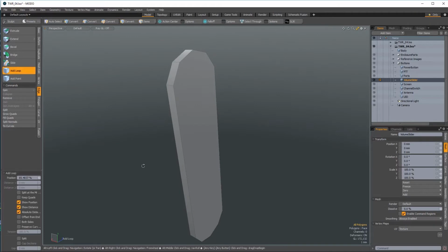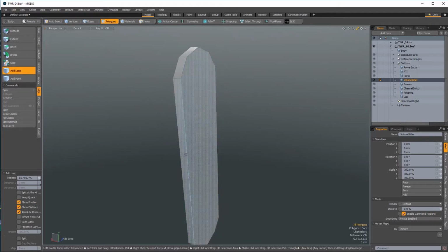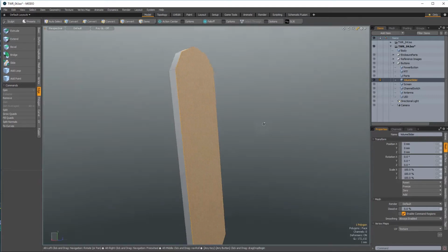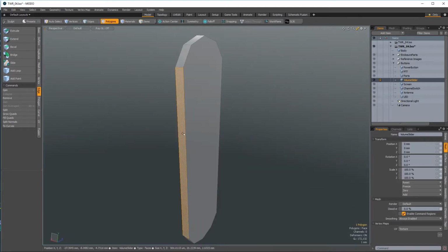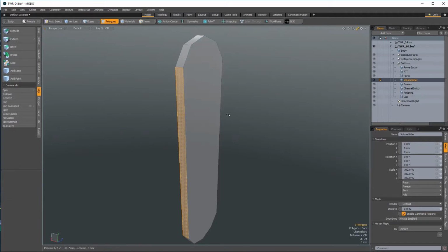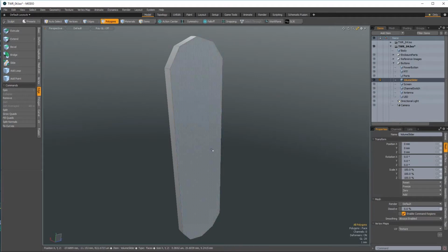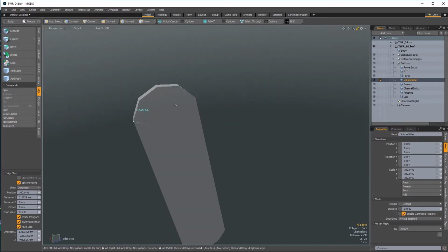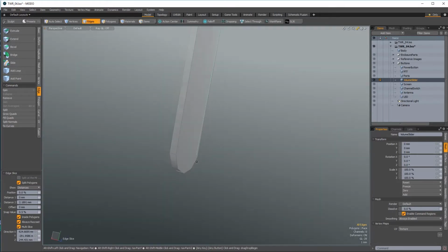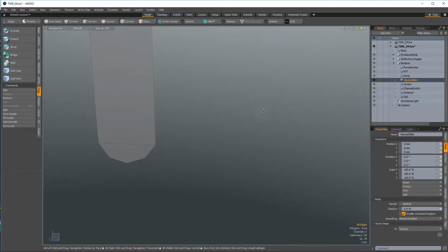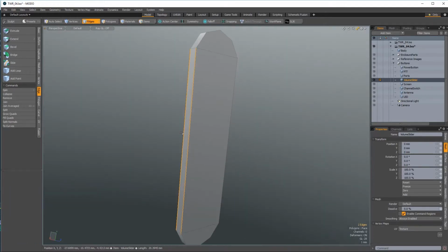And so I'm going to need some edge loops, but an add loop or a loop slice isn't going to slice through this because this is actually a large n-gon. So if we try, and I'll show you, Alt C, it's not going to slice all the way through. So we need to resolve this n-gon a little bit. So I'm going to cut from here to here. And I'll do the same on the bottom. And that should resolve things.